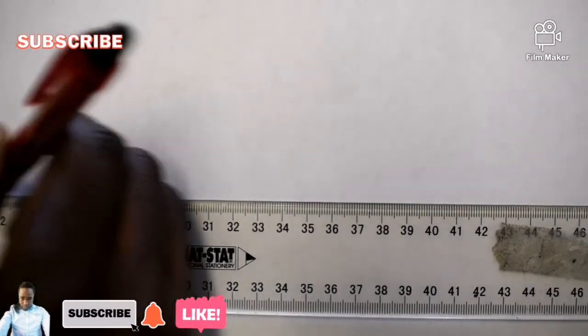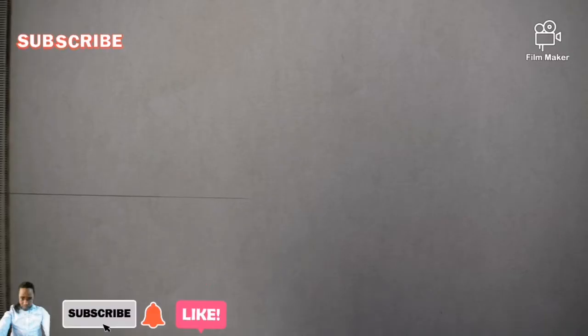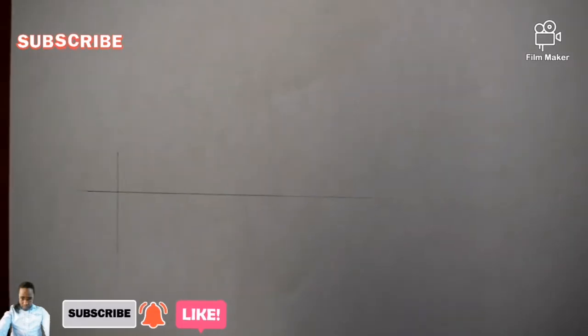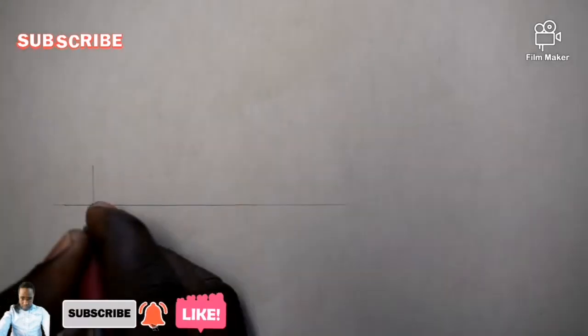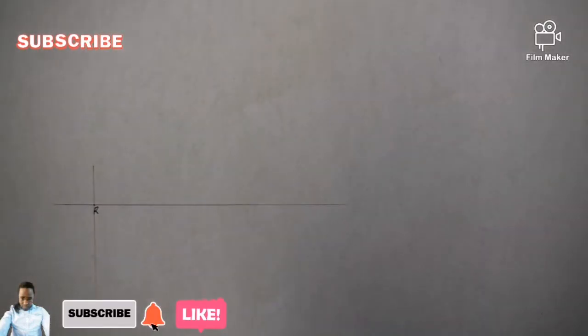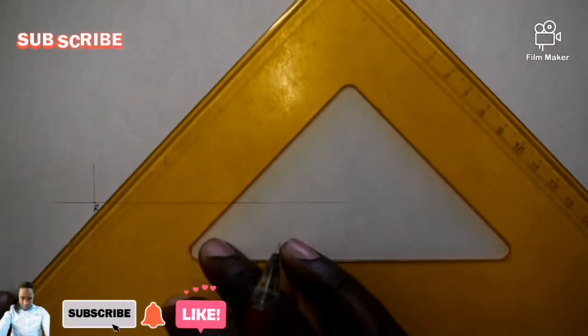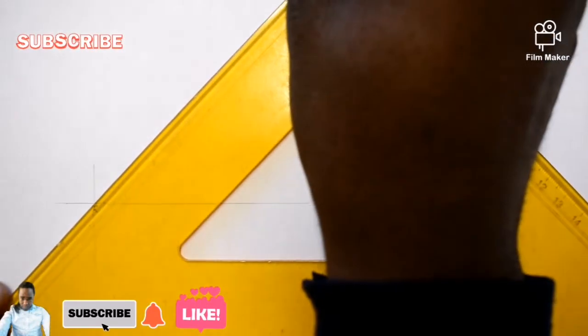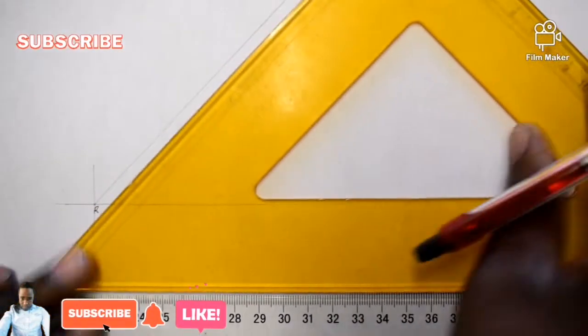Then I'll start with the horizontal line going this direction and perpendicular against this one. Where they are perpendicular to each other, I am going to say this is my point R. Then at point R, I take the 45 degrees set square and draw this line faint.